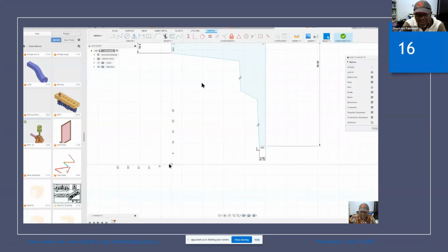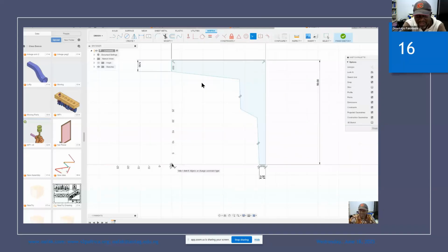And then you need to do a collinearity with the origin. If you take the collinear tool there, collinearity with the origin, those 2 points, collinear with the origin, it forces that to be on the axis, on the x-axis. Okay, so you can still use that, force that to be horizontal, force that to be vertical, then force that also to be vertical. And then the vertical distance in there, that's an error.